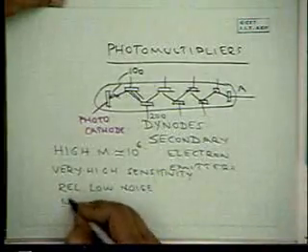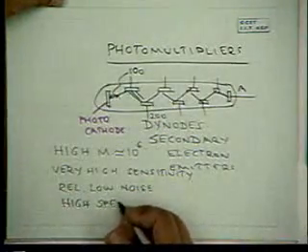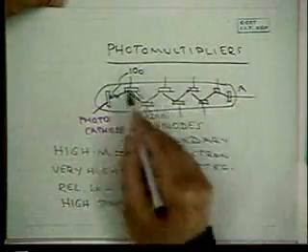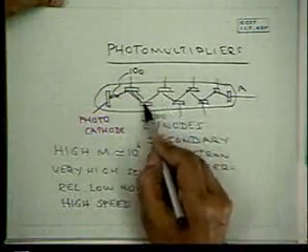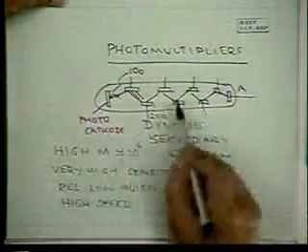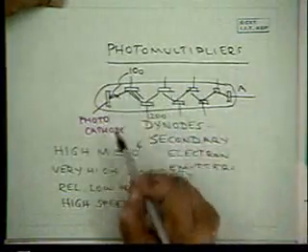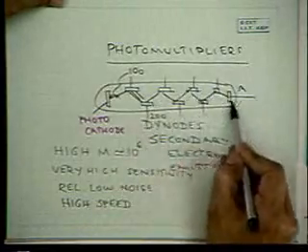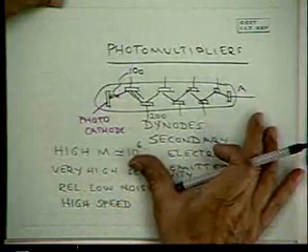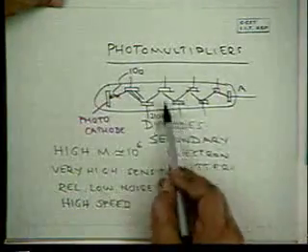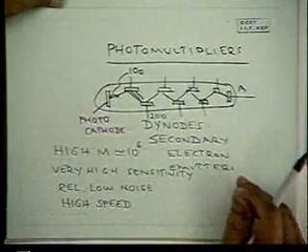And one can get reasonably high speed if these devices are properly designed, with very high voltages, so the transit time is less. This is obviously not going to be as fast as solid state photodetectors, because some time is required for electron transit. Okay, there will be some delay because of this transit, but if the delay is constant, then it does not add to any signal distortion.